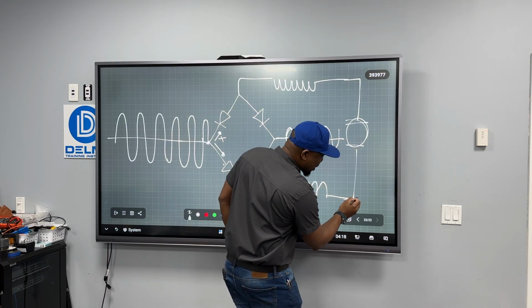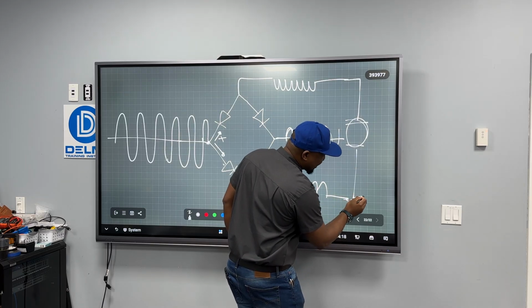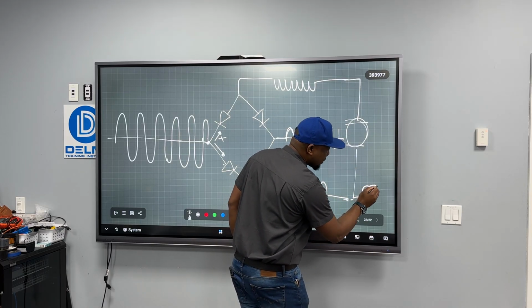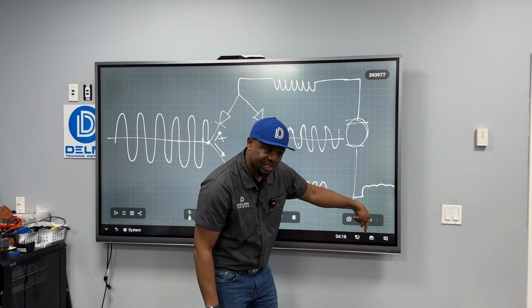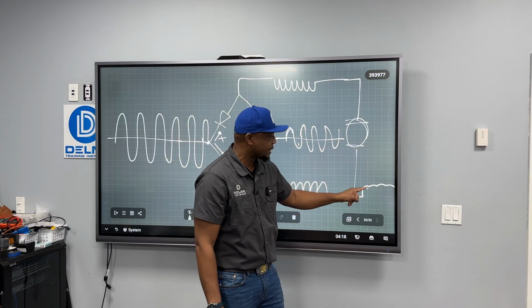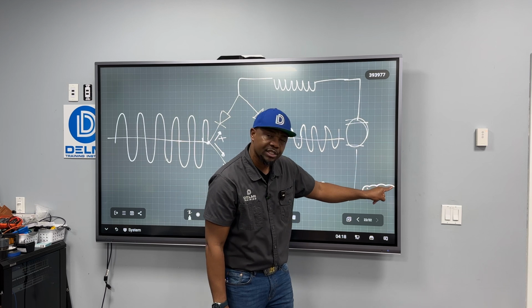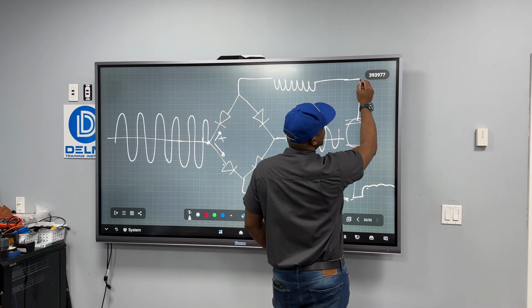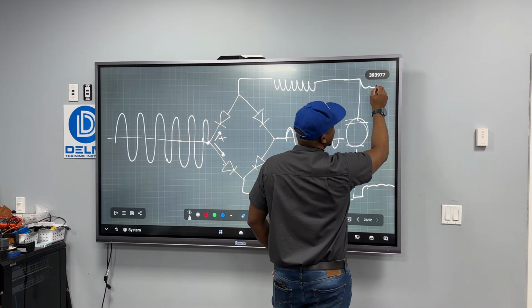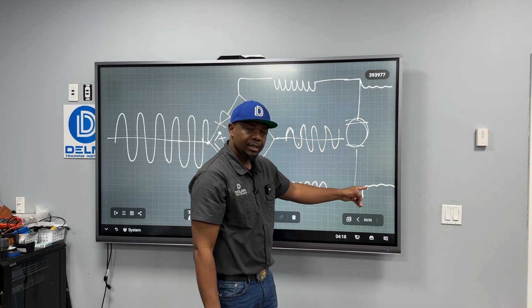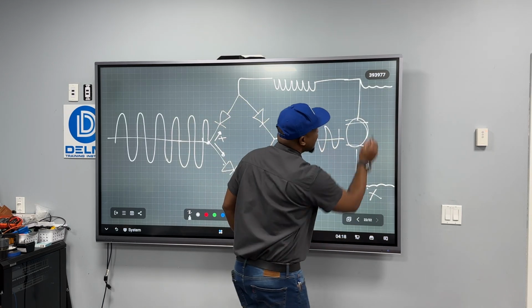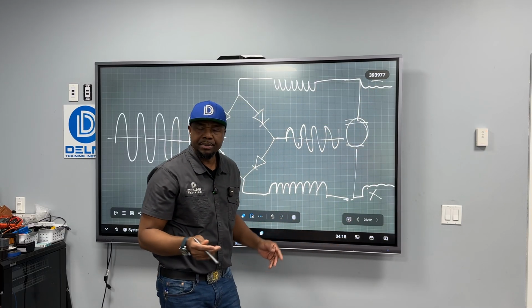So what we're going to end up with from here, after we've connected the capacitor, is this. Anytime it tries to discharge, the capacitor fills it in. So we're going to have near straight. And when you look here too, it's going to behave the same way. And that's how we're able to have the positive and the negative voltages being rectified.